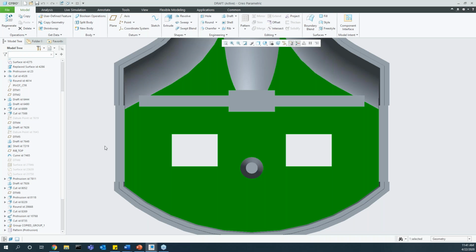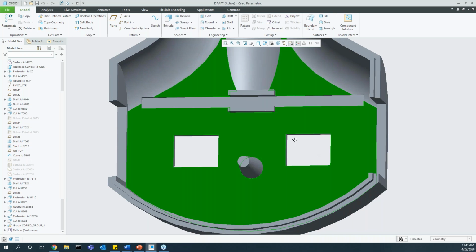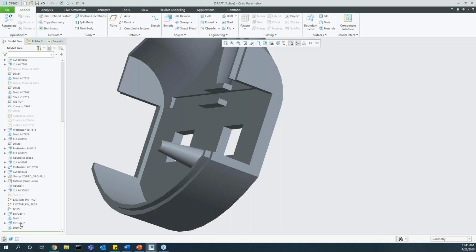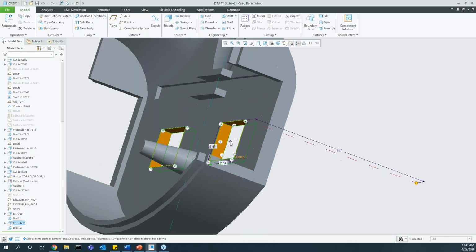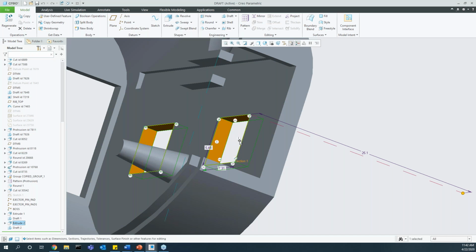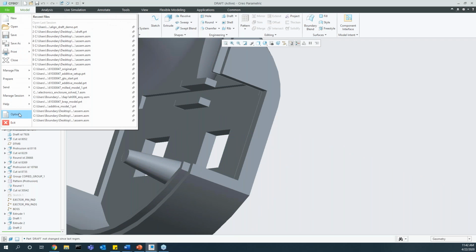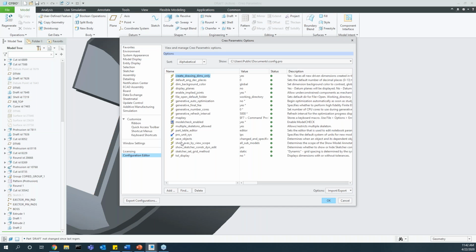Next thing we have is showing the extrude options. So if I edit dimension options, if I just look at this extrude 2, I can edit dimension. And now we have the capabilities of seeing the constraints used along with the dimensions. This gives us greater control, greater ease of just seeing our design intent without having to go in and edit definitions of things.